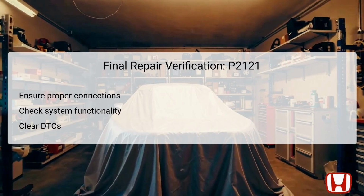After all necessary repairs and replacements related to DTC P2121 have been completed, it's vital to conduct a final verification step. Begin by ensuring that all connections, especially at the APP sensor and PCM, are secure and free of corrosion or damage. Next, check the system's functionality by performing a test drive of the vehicle, particularly monitoring the accelerator pedal response during various driving conditions. This will allow you to confirm that the engine behaves appropriately, with no hesitation or warning lights present.